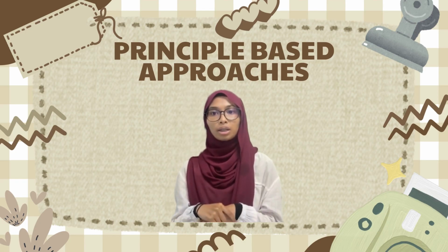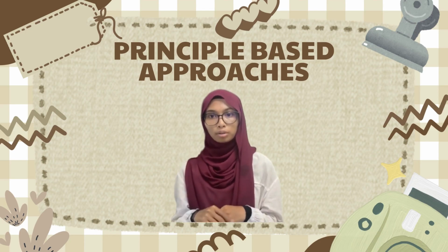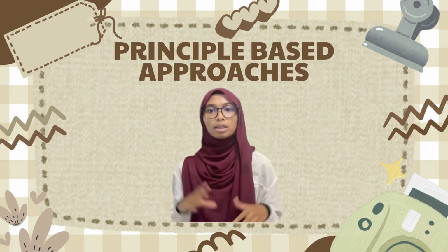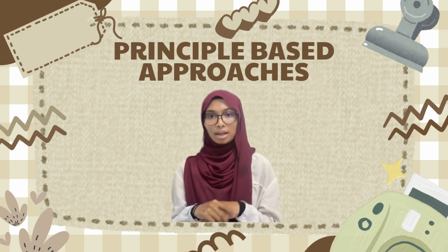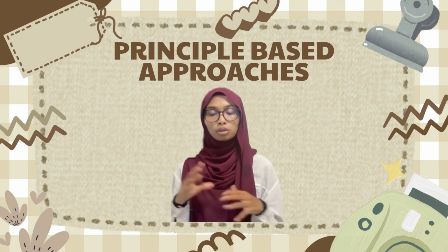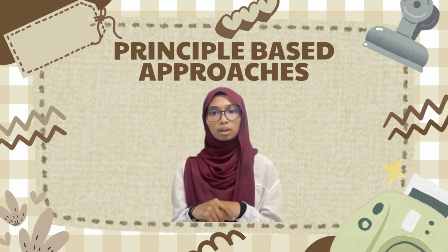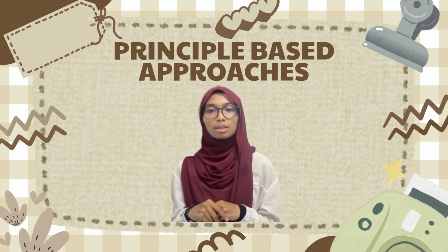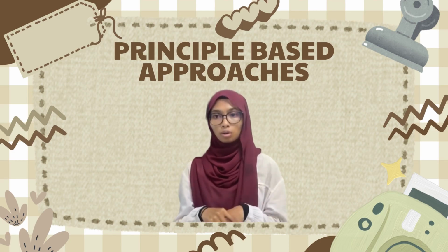The differentiator naturally amplifies high frequency. A 100 picofarad capacitor is added to limit the high frequency gain. This made the circuit stable and able to ignore the noise. The summing amplifier can only change its output voltage so fast. The circuit should work fine at 3 kHz, but that is too fast. The op-amp couldn't change its voltage fast enough to keep up, leading to distortion.